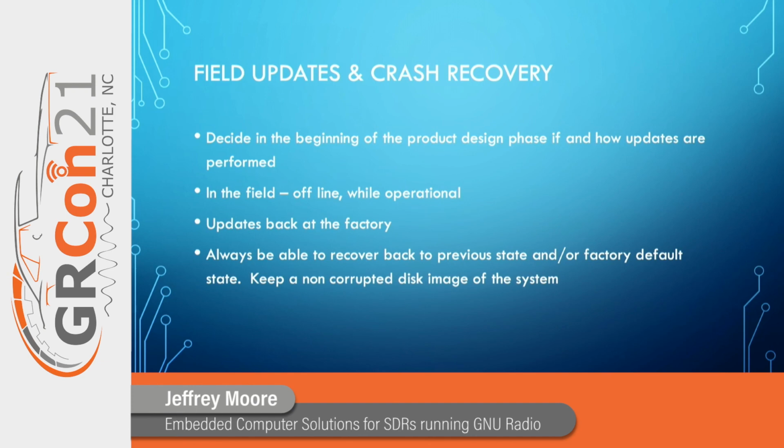I won't dwell on this, but field updates and crash recovery have to be designed in with the same thought. You know, how you want to update your product in the field. Do you ever want to update the OS? Do you want to update your application? Do you want to update data? Do you want to download data? How do you want to recover from crashing? Do you have an extra set of images on your SSD in a very protected area that you can reload if things do go awry, either in updating or in operation? So that's something that needs to be thought of from the very beginning.